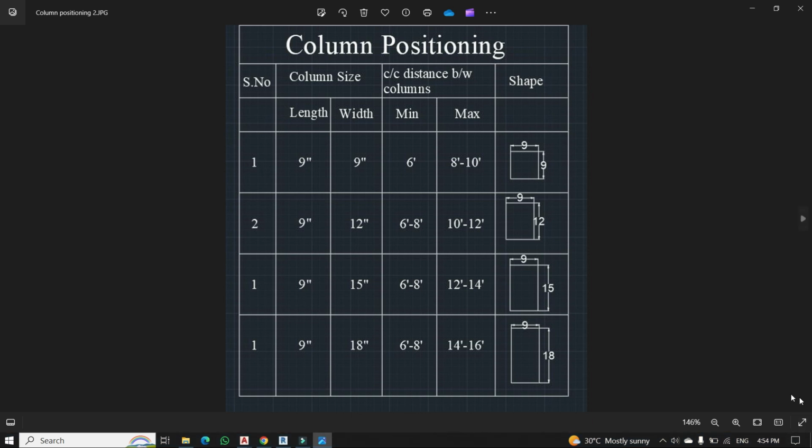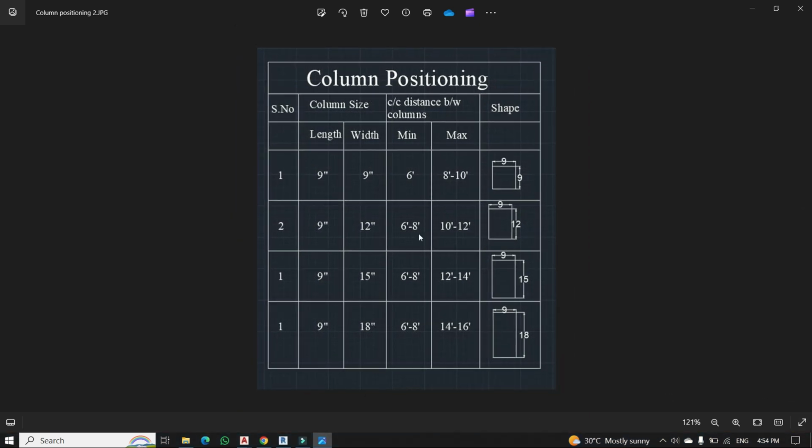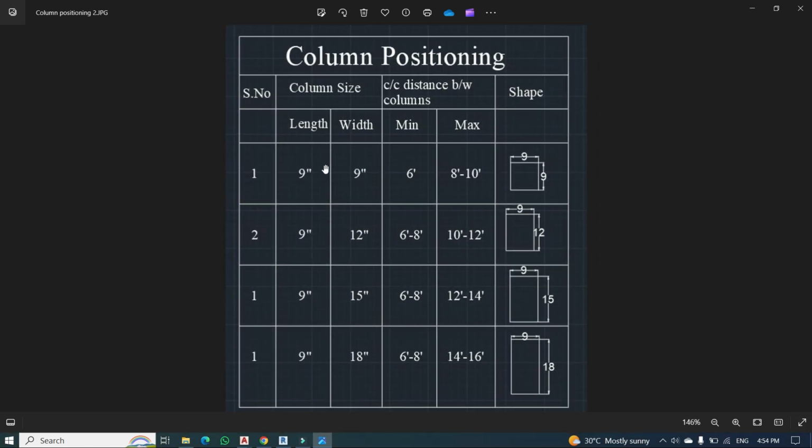So if you want a vertical member to bear the load of the slab, directly the column is not going to take the load of the slab. So the load of the slab is going to be transferred to the beam first. Okay. Then from the beam the load is transferred to the columns. So a load distribution pattern will be there.